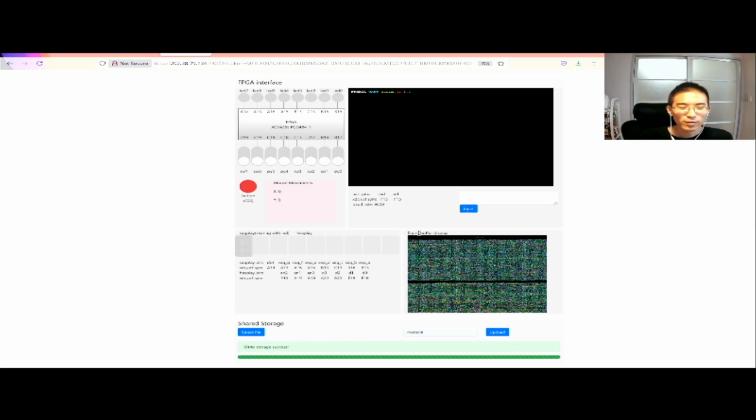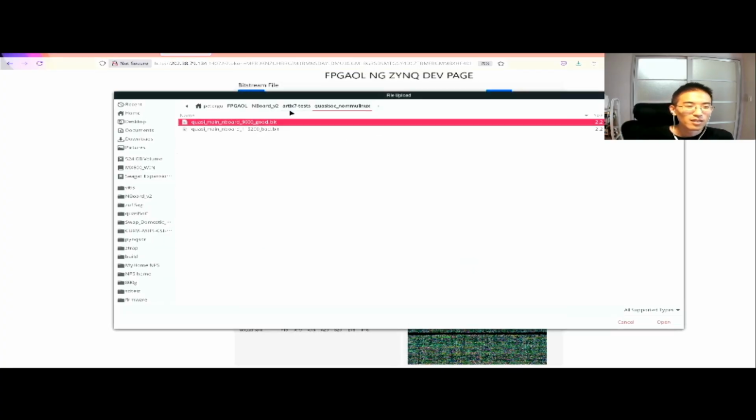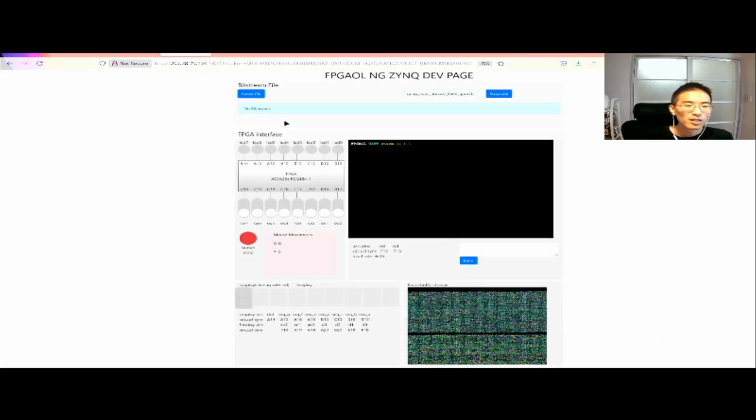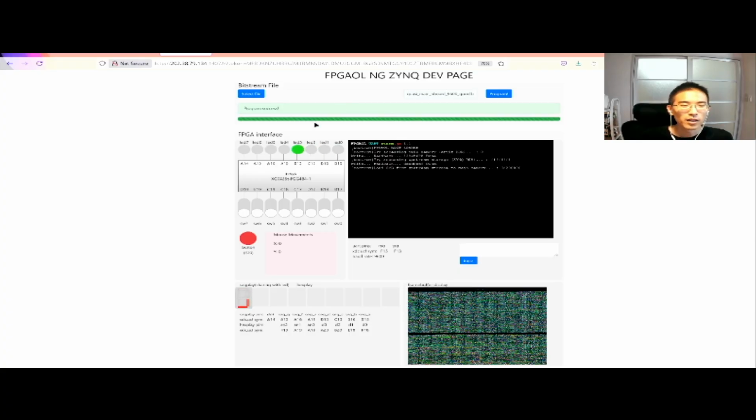Now this is finished, and you can see already this frame buffer display is just a map of the memory, so it will literally show what this firmware looks like in the memory. Then we're just gonna upload the bitstream to the Artix 7. We can see that the RISC-V processor is loaded and the LED starts blinking.